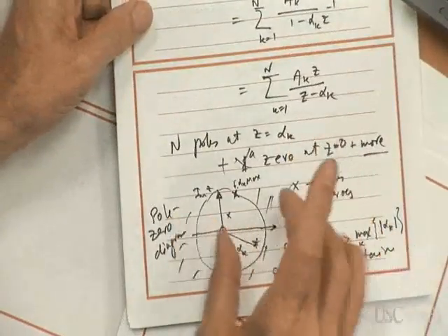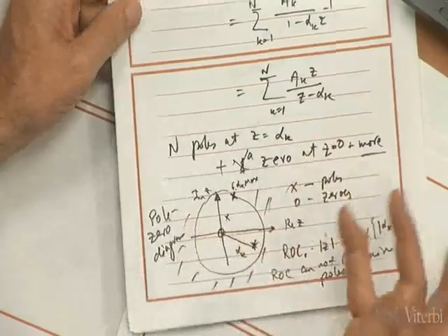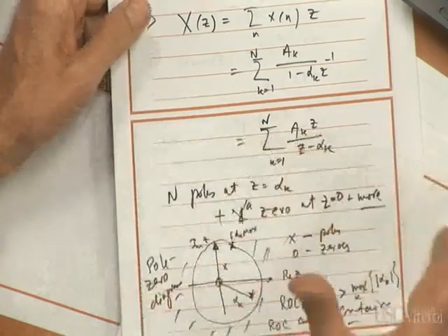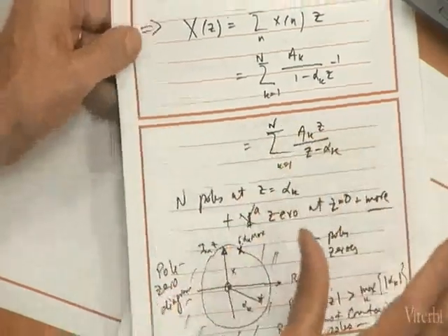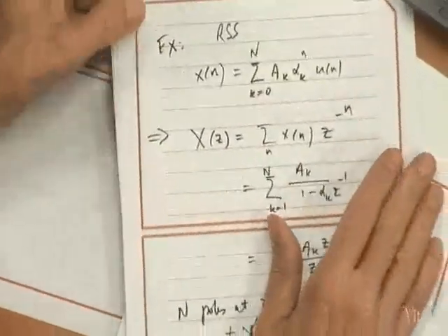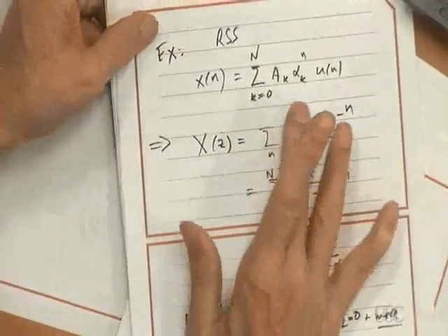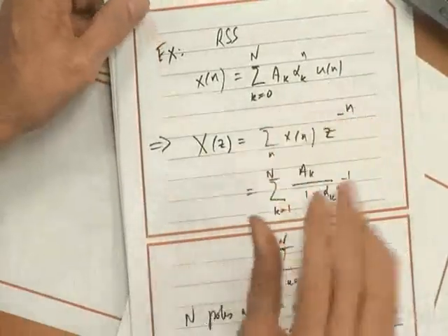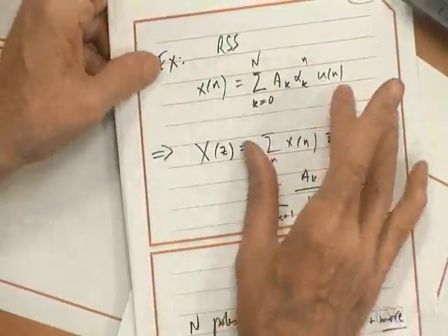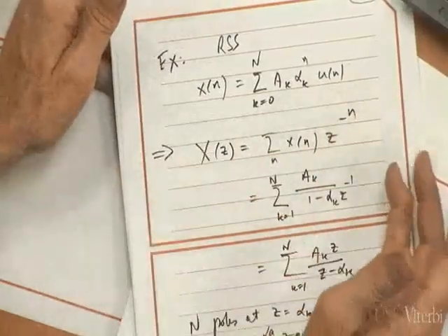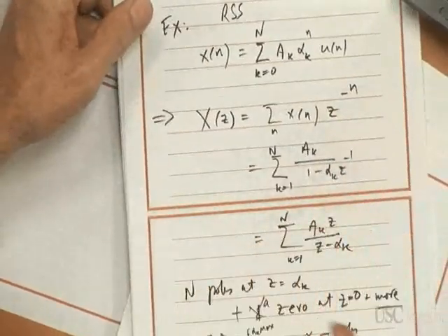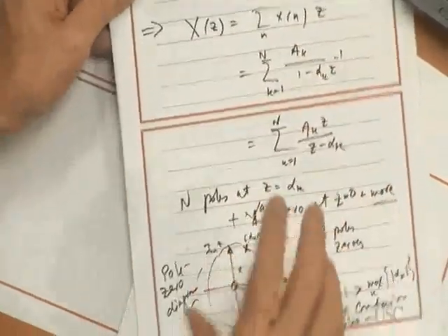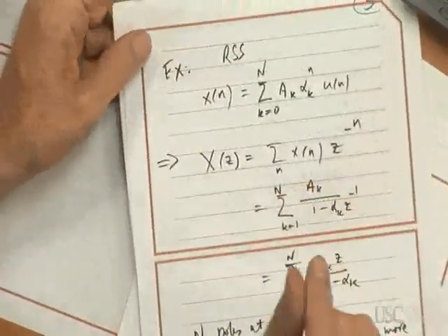The Z transform may converge, and we say the region of convergence includes infinity or not. By that I mean it may converge as z goes to infinity, or it may not. Very interestingly, it depends on whether the sequence is causal or not. If the sequence is 0 for n less than 0, then the Z transform does converge as z goes to infinity, so we would say the region of convergence includes that.